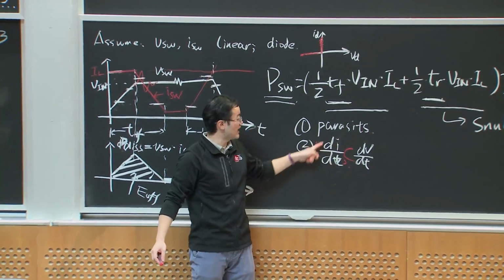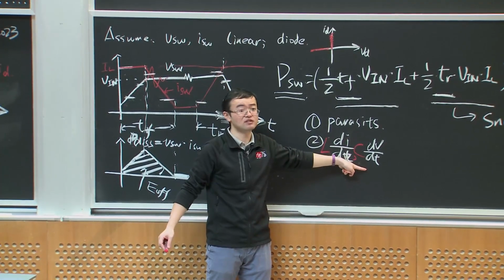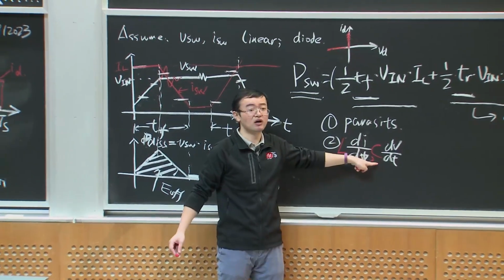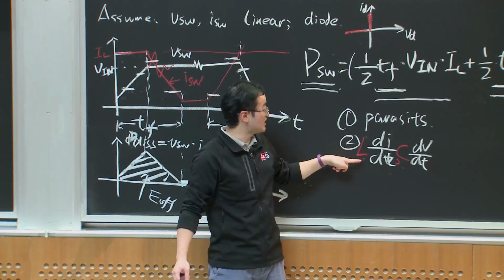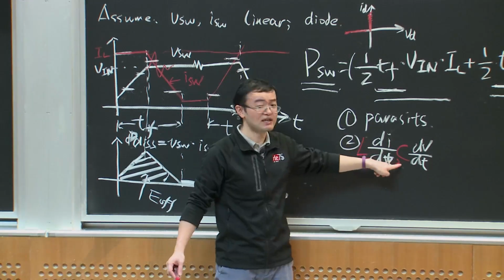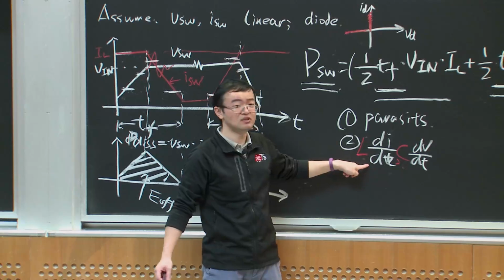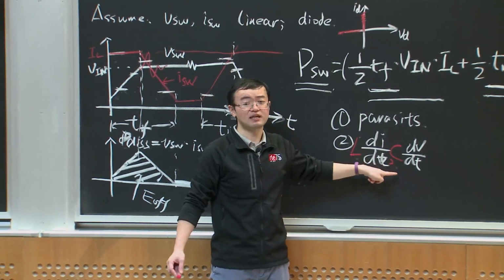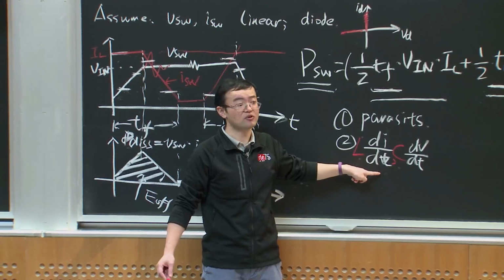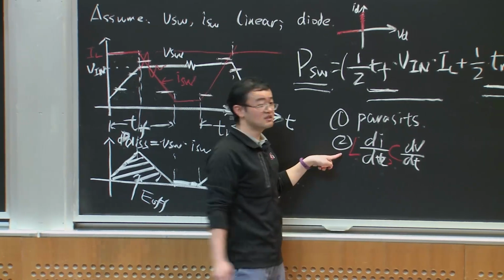Previously, if we had dI/dt or dV/dt pretty small and our parasitics pretty small, these things would not matter to our control circuit. But if we have a large inductance or a large capacitance together with a large dI/dt or dV/dt, this voltage or current is unexpected. They can cause some errors for our control circuit. So this is the second limitation.